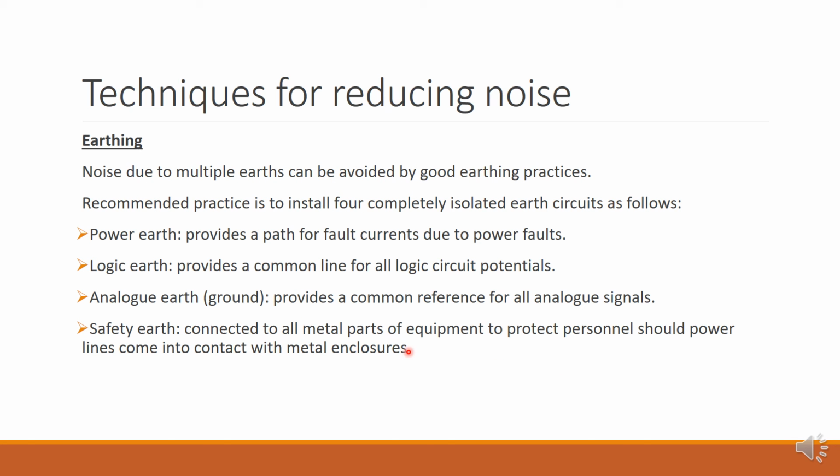Another technique for reducing noise is to take care of grounding and earth. Earthing is very important. Noise due to multiple earths can be avoided by good earthing practice.